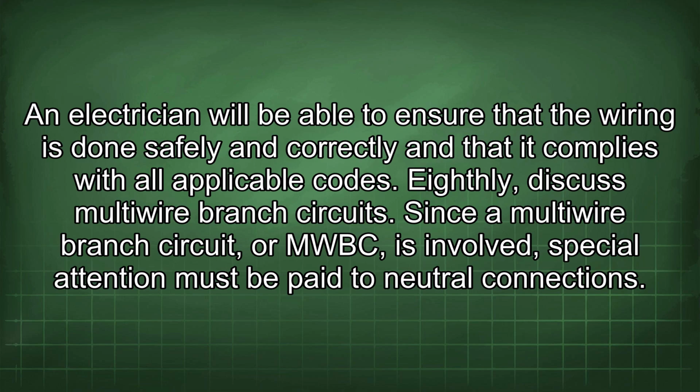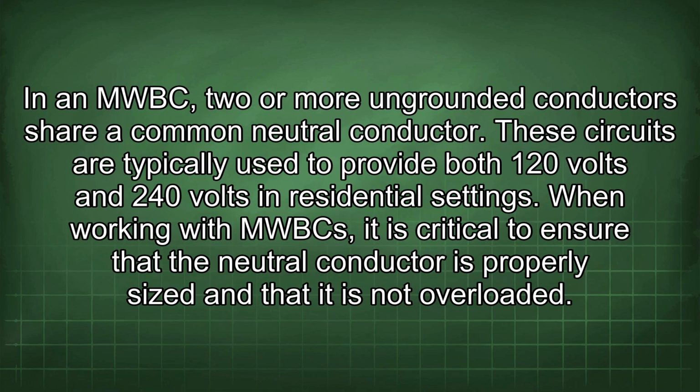Since a multi-wire branch circuit, or MWBC, is involved, special attention must be paid to neutral connections. In an MWBC, two or more ungrounded conductors share a common neutral conductor. These circuits are typically used to provide both 120 volts and 240 volts in residential settings.